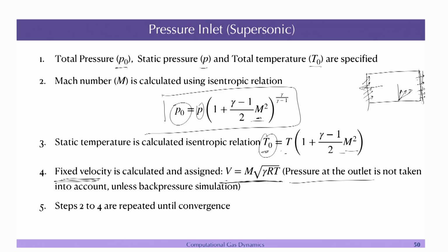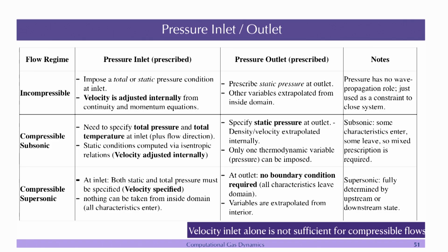For example, what happens in scramjet unstart. You have the pressure increasing, and because of the increase in the pressure, you have the shocks traveling upstream, and that leads to unstart. Right. So, this is the supersonic flow, everything presented in terms of a table.